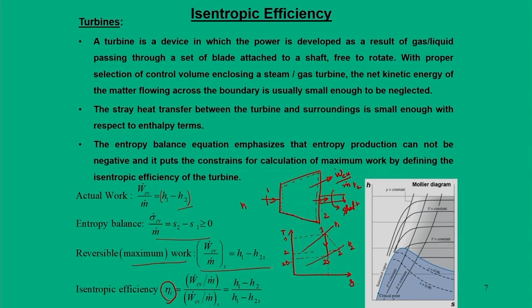So, here let us talk about something else: the isentropic efficiency is expressed in terms of enthalpy, and when you use steam, normally the expression is a general term. When you talk about a steam turbine, we refer to the diagram that we call a Mollier diagram. Here is a snapshot of this Mollier diagram which you can represent.